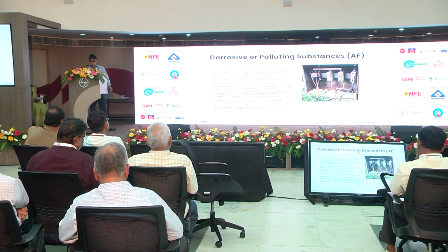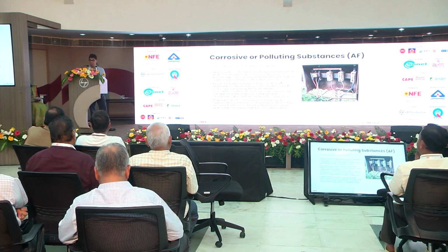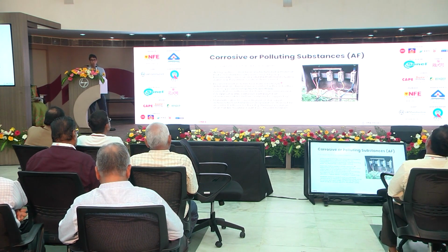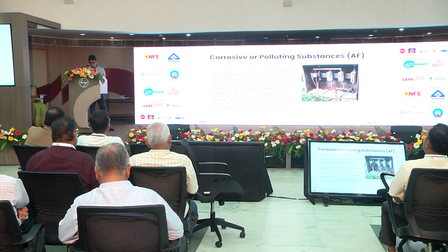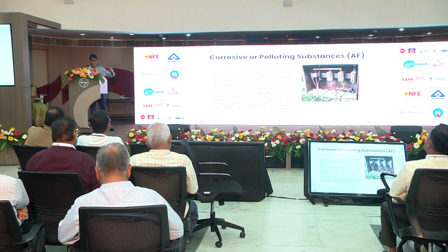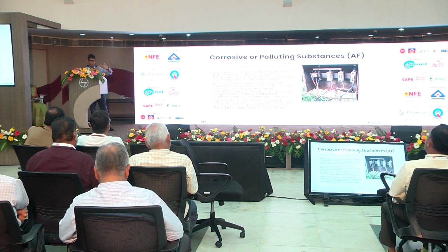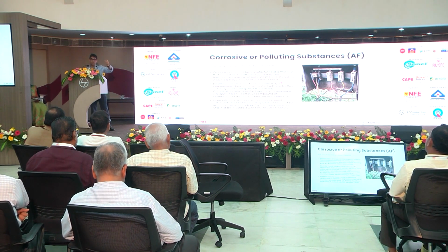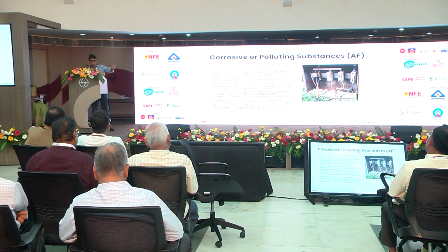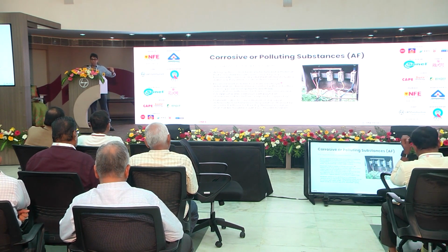Another thing is dissimilar metals. So a lot of you are aware, I'm sure, that you have copper cables and aluminum cables. Now, most terminals on equipment or terminal blocks are brass or copper, some sort of copper alloy. So it's very important that the anti-corrosive compound is applied, which prevents the oxidation of the aluminum. Because if you have dissimilar metals, the electrons will jump from one metal to the other, which will cause corrosion.